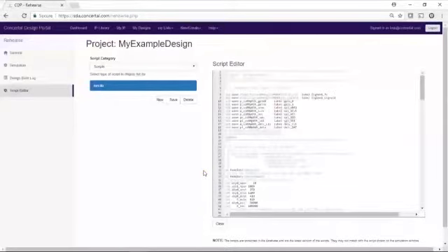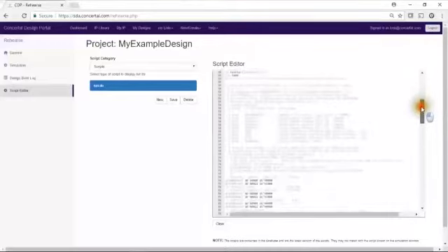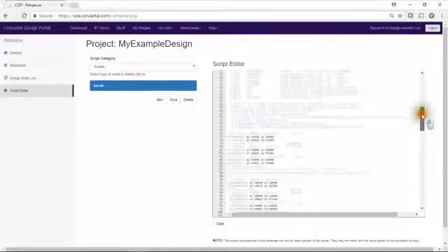Line 31 initializes some procedures that we want to use for reading and writing internal registers to make it easy for us to control the simulator engine. And the defaults are things such as the power on reset settings and default clock frequencies, which we override with the set statements. There's also a script called initSim, which actually applies the power on reset circuitry, and we run for 5,000 ticks, and now the simulation is ready to accept application-based commands to operate the part.